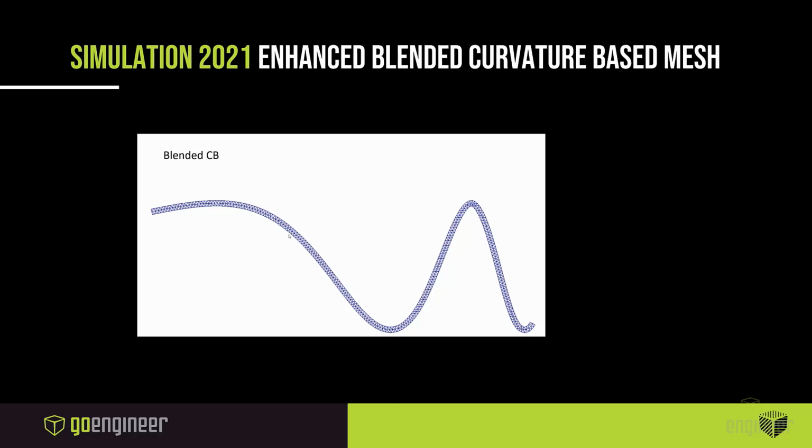We have a uniform mesh going through this cut strip of material that I have, 2 elements of thickness, and we have uniform elements throughout the length of this, which will also result in a nice smooth result, versus having our results clumped up in certain areas, and having our mesh data represent a better gradient of results versus having them in regions or non-discrete regions.